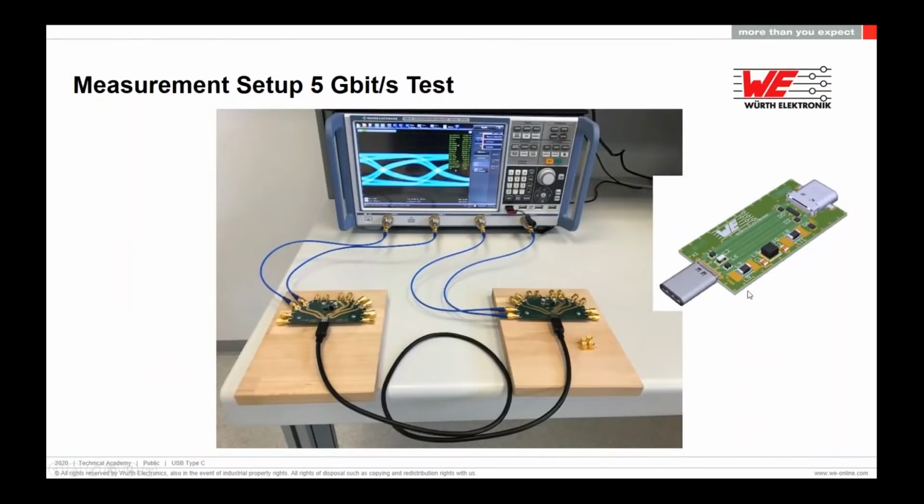So what we did, we created a dongle, which is intended for 5 to 10 gigabit per second. We show here that it's not critical to put in common mode chokes for better EMC and EMI performance, and ESD protection on this side to provide better ESD immunity. And we also provide here a 5-pole filter for filtering the power of 100 watts to get out the differential noise there, and also some ESD protection. And if you do a proper design, even with these components inside, it's not a problem to get 5 to 10 gigabit and more over the site for your data signal.